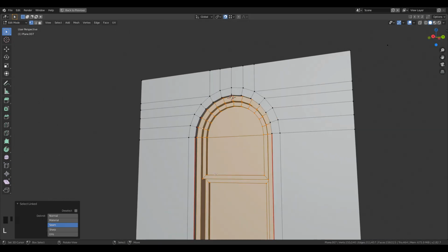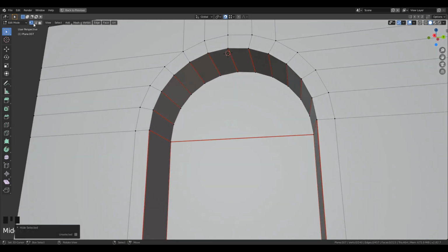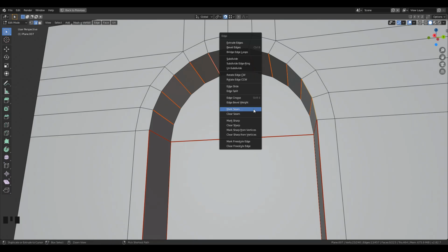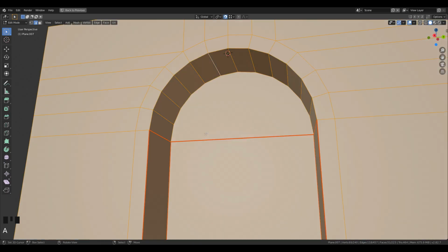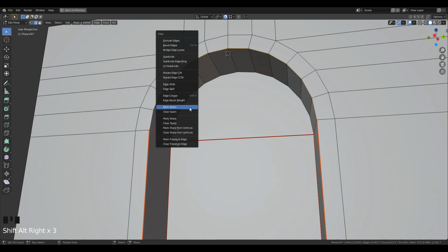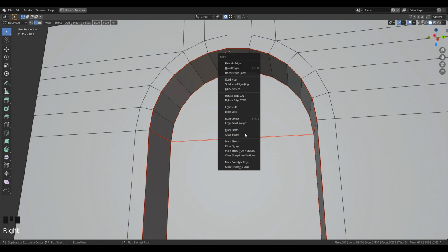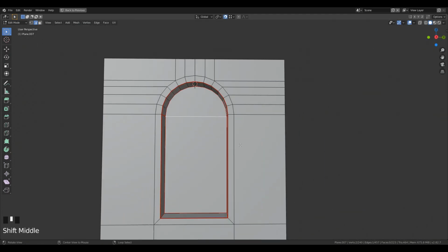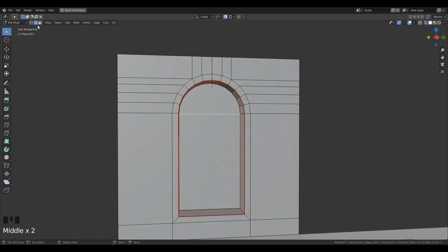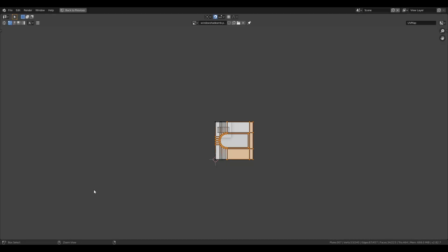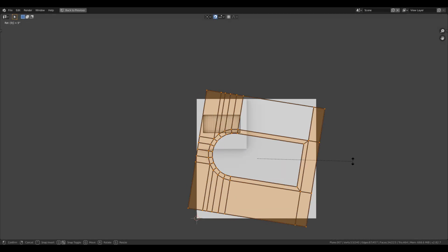After that, select the rounded edges which have marked seams on them, and press Ctrl E to select clear seams. Then just select the outer edges of the window and apply marked seams to them. Clear the seams that are on the plane surface and just leave marked seams after the faces or edges that start to curve after a 90-degree angle. Then just select the outer face of the window panel and unwrap them and rotate them if necessary.